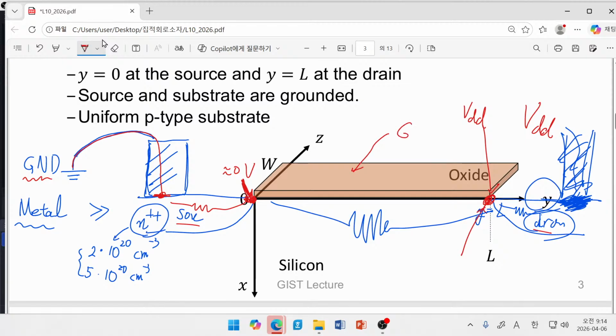Yes, here we have a gate, and underneath that gate we can find the silicon dioxide layer, which is extremely thin. Below that layer we can find a plane which is covered by the gate contact, and this part becomes quite important and is the electrically only meaningful part of our system.